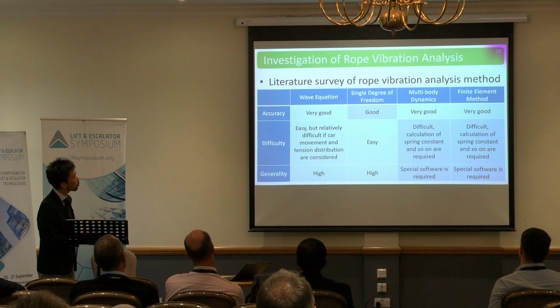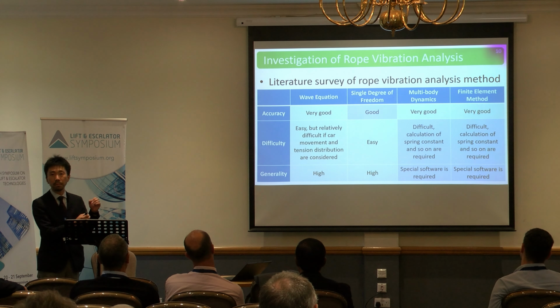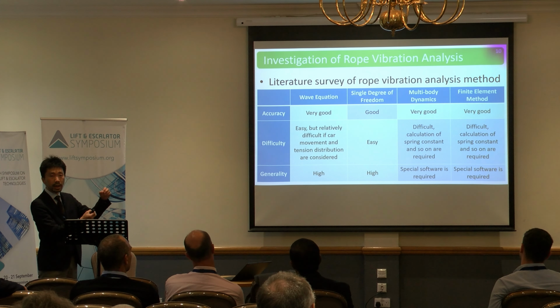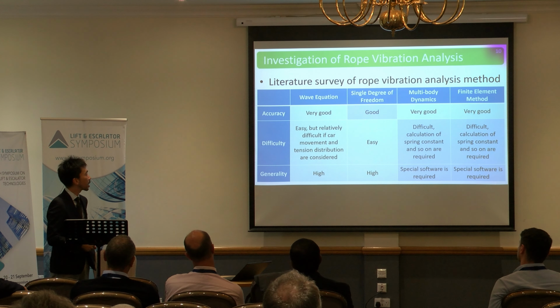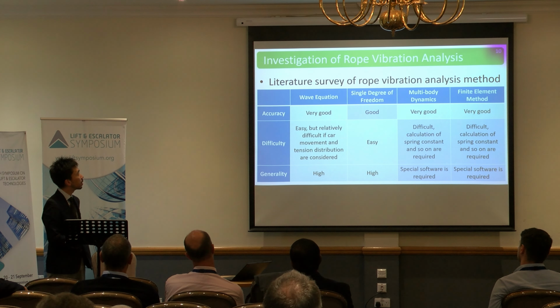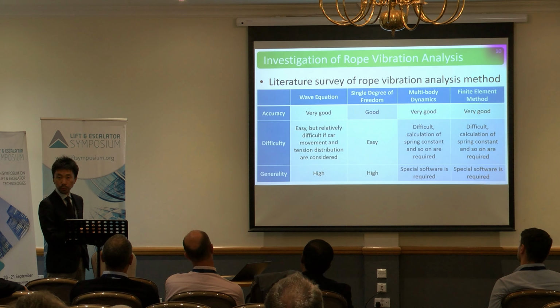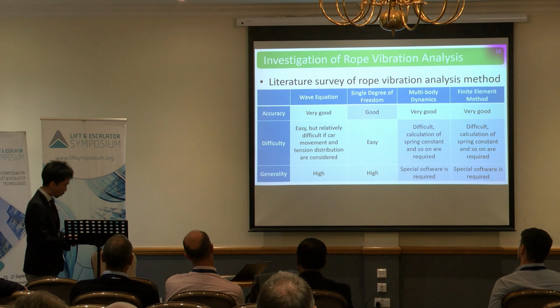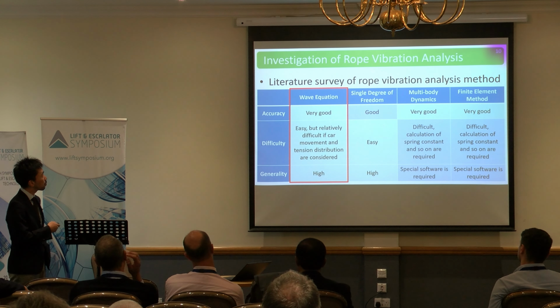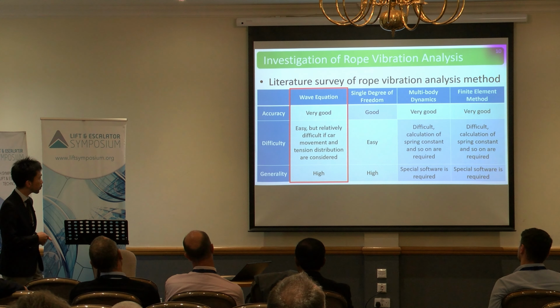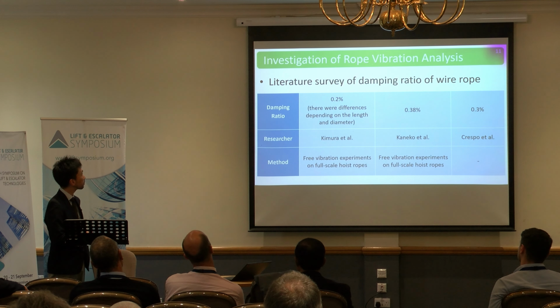However, multi-body dynamics and the finite element method require special parameters, like a spring constant between points of the wire rope, to calculate the response. They also require special software to calculate. So in our working group, we applied the wave equation to calculate the vibration.